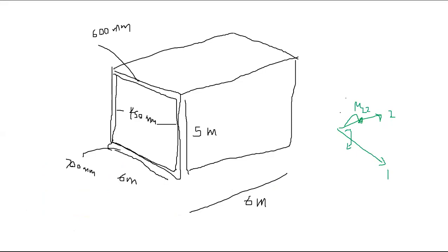So this bending moment is actually about the axis 1, right? The direction is like this, right? So if you get this idea, this is the second direction, this is M22. Now you can't see M11 because it's coming from the plane or going in towards the plane, right? So this is given by, it's not like the beam. In the beams, if the axis is X, you take either the Y or Z axis to define My or Mz. So this is totally different, right? So along the road, the moments will give that sagging or hogging by M22, right?